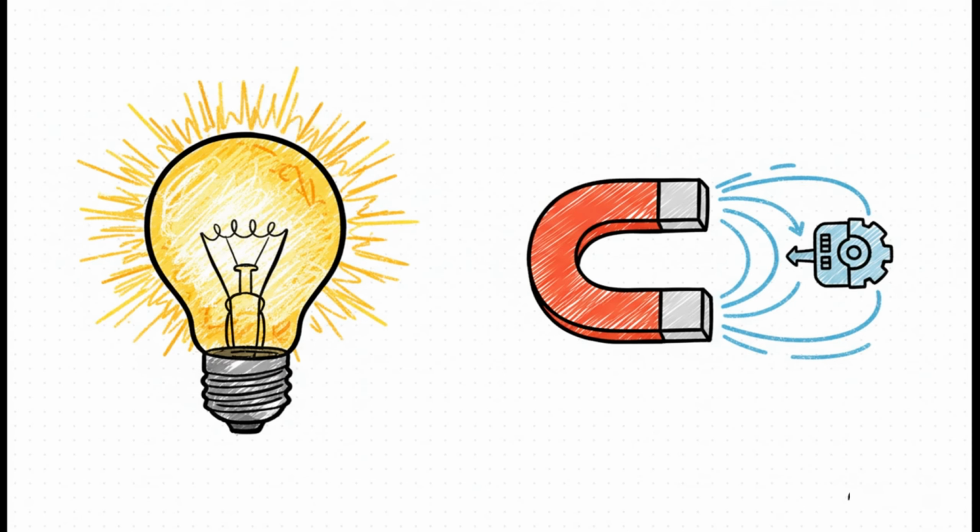To really get this, you need to know about two different types of power. First up is real power, measured in kilowatts. This is the good stuff, the working power that actually lights up a room or spins a motor. But then you've also got reactive power, measured in kVAR. Think of this as magnetizing power. It doesn't do any useful work itself, but it's absolutely essential for creating the magnetic fields that things like motors and transformers need to run.